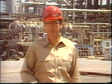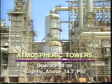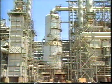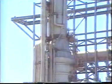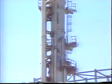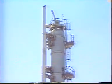Distillation columns are often classified according to the operating pressures they maintain. Crude units, like this one, are often called atmospheric towers because they operate at or slightly above atmospheric pressure. Other towers which process very light materials may operate under hundreds of pounds of pressure. The high pressures are needed to keep the products in a liquid state so they can be more easily stored and transported. Many pressure towers are designed with narrow tops because there is less vapor-liquid traffic in this portion of the column, and this design helps maintain the desired operating pressure.